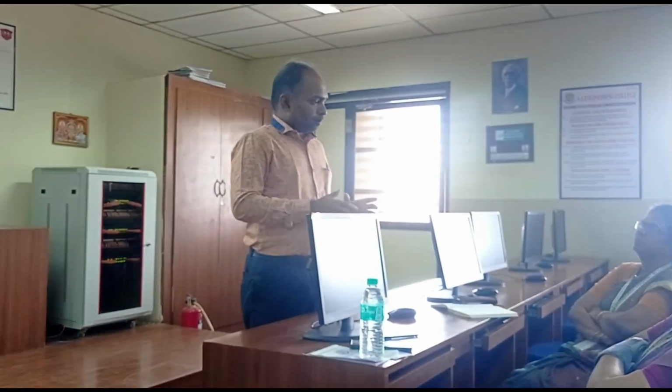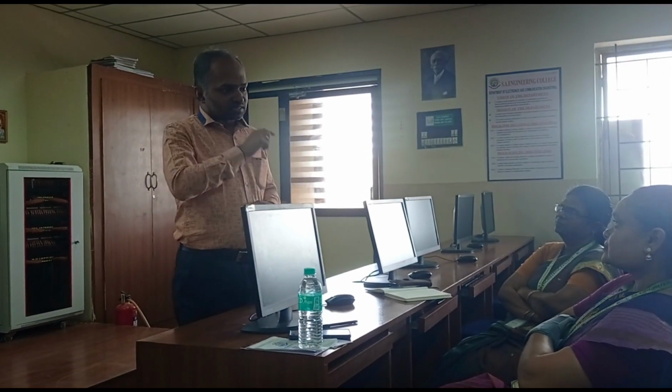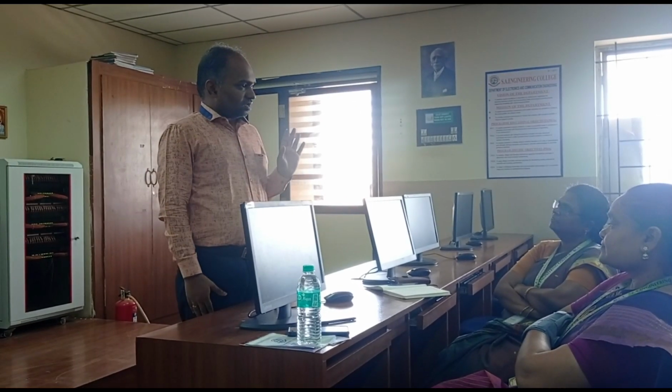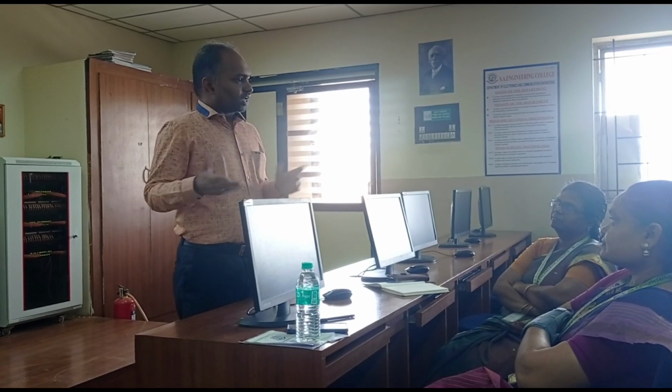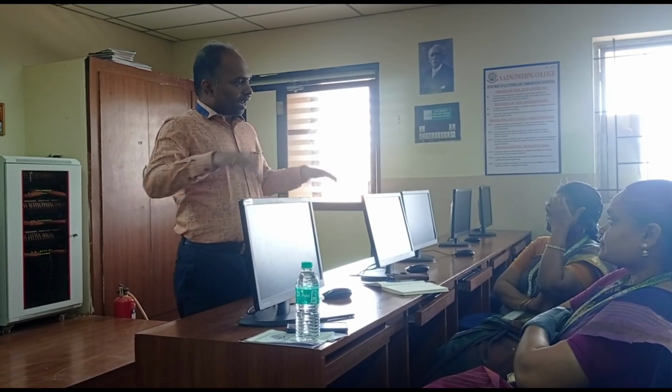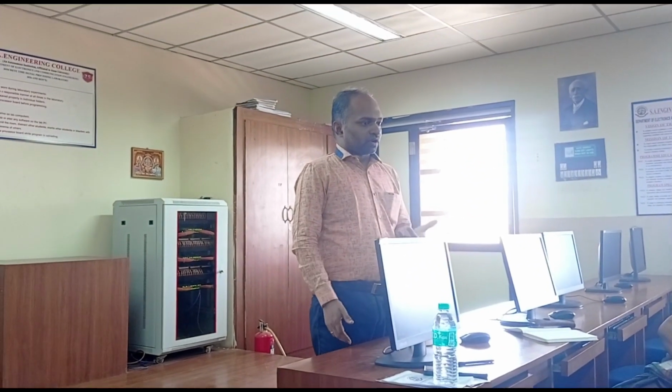will be more. Because in FPGA, you have 300K complexity. For every 300K, you have dedicated space in the cell. So every space will consume some amount of power, whether you are using it or not. We are using only 12 gates, but the area is already consumed. You cannot avoid that because it's already a general purpose IC. You cannot modify the FPGA according to your requirement.